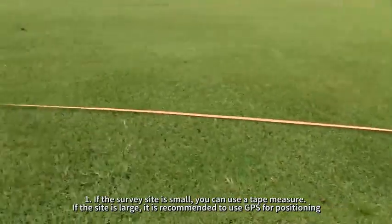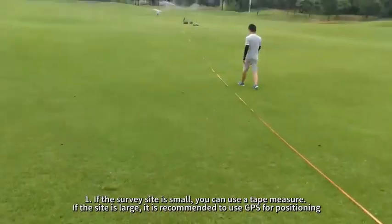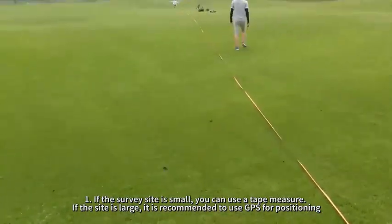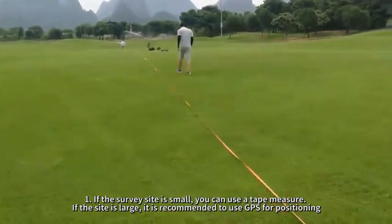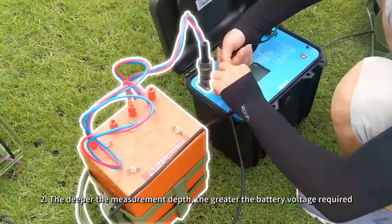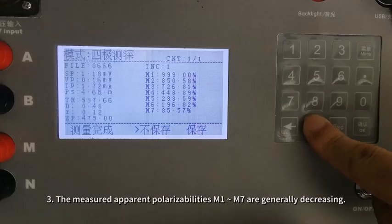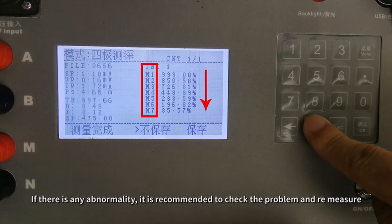Matters needing attention. 1. If the survey site is small, you can use a tape measure. If the site is large, it is recommended to use GPS for positioning. 2. The deeper the measurement depth, the greater the battery voltage required. 3. The measured apparent polarizabilities M1 to M7 are generally decreasing. If there is any abnormality, it is recommended to check the problem and remeasure.